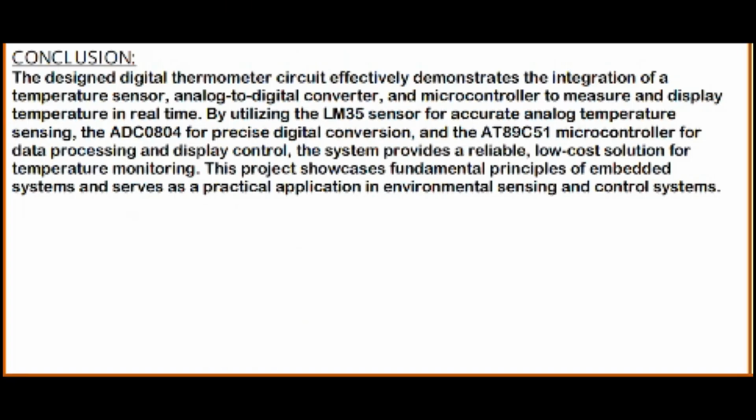Conclusion: the designed thermometer circuit effectively demonstrates the integration of a temperature sensor, analog to digital converter and microcontroller to measure and display the temperature in real time, utilizing the LM35 sensor for accurate analog temperature sensing, the ADC0804 for precise digital conversion and the AT89C51 microcontroller for data processing and display control.